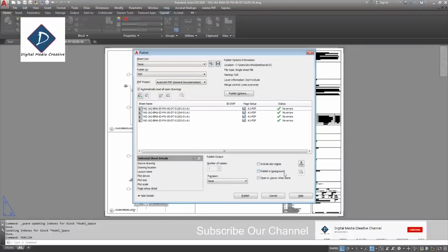So everything is done. Also make sure this publish in background is unticked. If it's ticked, all the process will be done in background. The thing is, if there is any error, you will not be noticed until it's finished. Okay, so make sure it's unticked. So I'm just clicking publish.